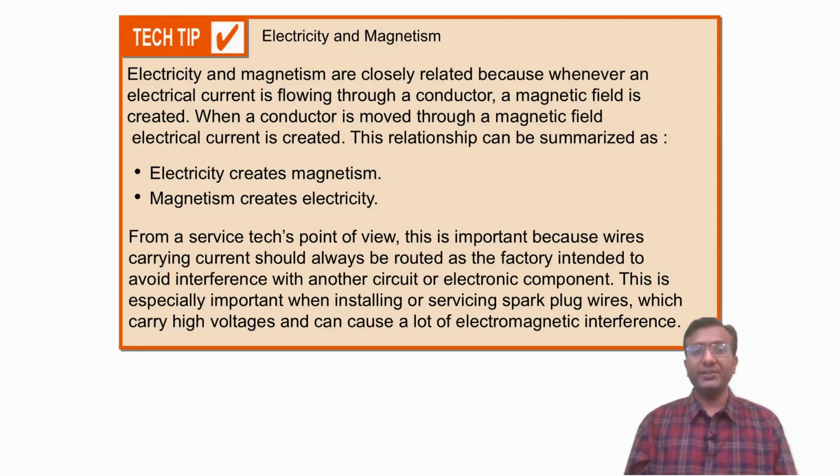From a service technician's perspective, this is crucial because wires carrying current should always be routed as intended to avoid interference with other circuits or electronic components. This is especially important when installing or servicing spark plug wires, which carry high voltages and can cause significant electromagnetic interference.